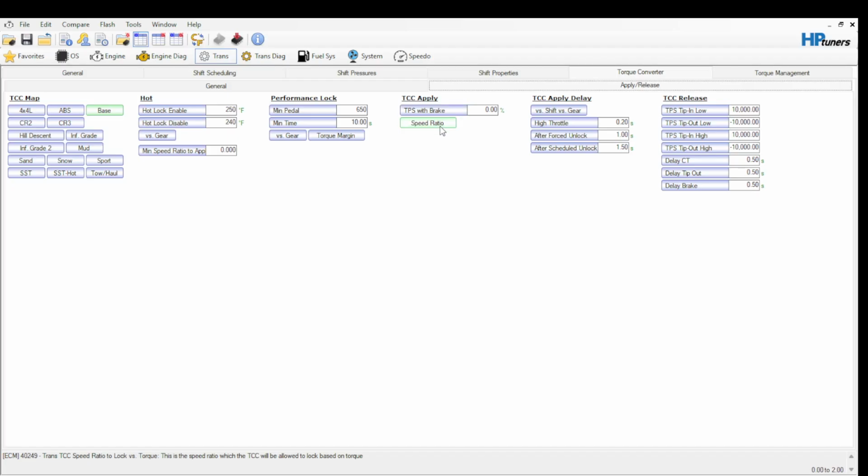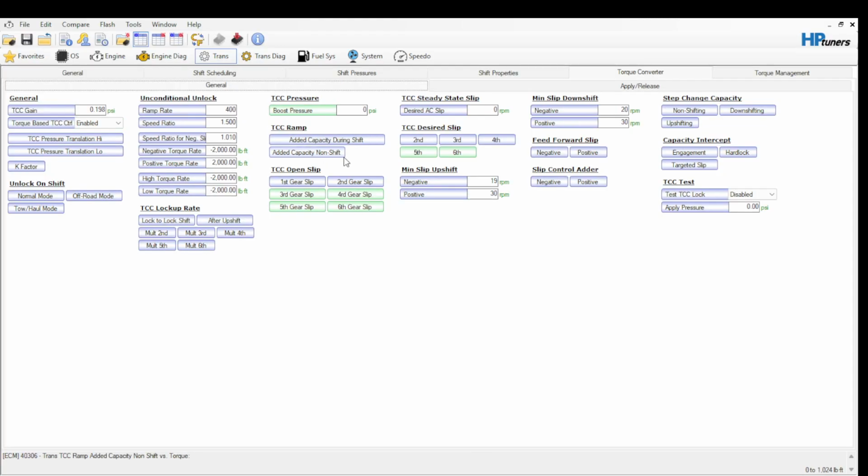So I wanted the truck to be more snappy down low because it kind of feels sluggish. And then because I have more torque down low, because I have changed the fueling and the way that the turbos work and the turbos themselves, I wanted to change the speed ratio so it doesn't just push the engine up to 3,000 RPM and make 5 pounds boost to get the same torque it could have made at 2,000, right? So I changed the speed ratio and then changed the torque converter map accordingly. That's something you're going to have to learn to do, not something you can necessarily go out and drive to do. I don't think that's realistic to dyno.